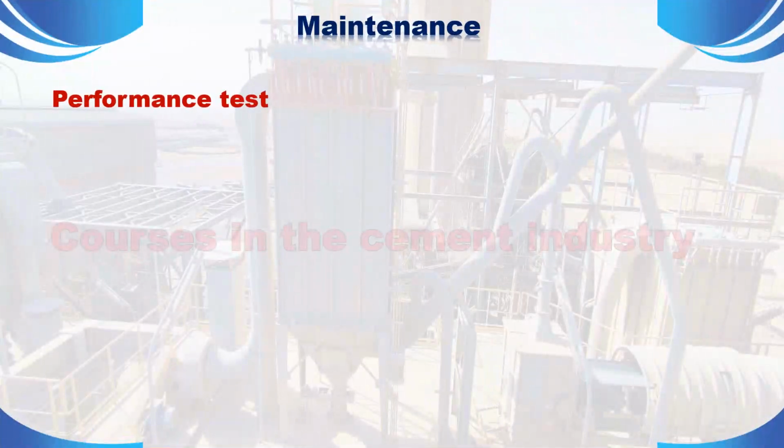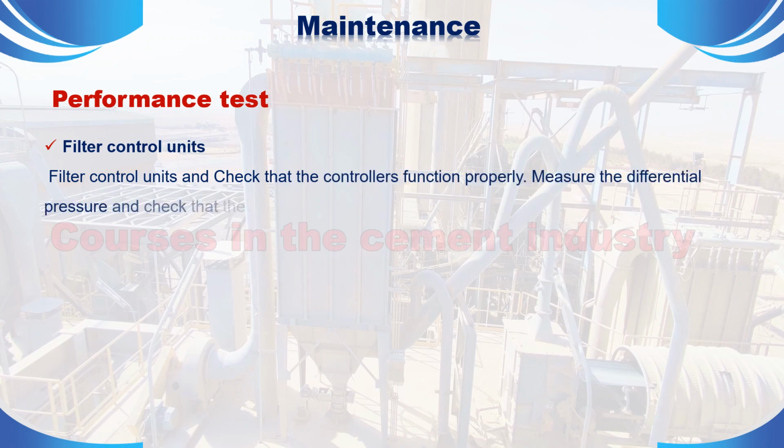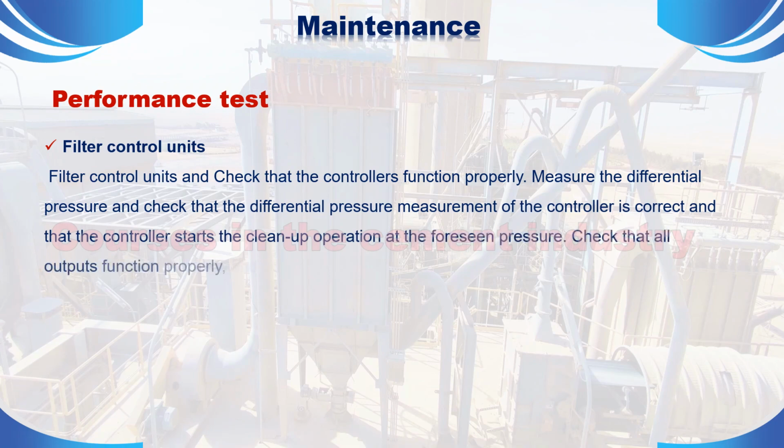Performance test. Filter control units. Check the filter control units and that the controllers function properly. Measure the differential pressure, and check that the differential pressure measurement of the controller is correct, and that the controller starts the cleanup operation at the foreseen pressure. Check that all outputs function properly, and that all bag rows are cleaned.